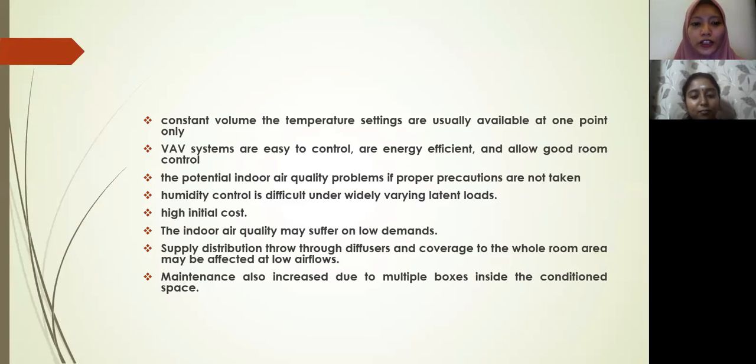There are potential indoor air quality problems if proper precautions are not taken. Humidity control is difficult under widely varying latent loads. It has a high initial cost. The indoor air quality may suffer on low demands. Supply distribution through the diffuser and coverage of the whole room area may be affected at low airflows. Maintenance also increases due to multiple VAV boxes inside the conditioned space.